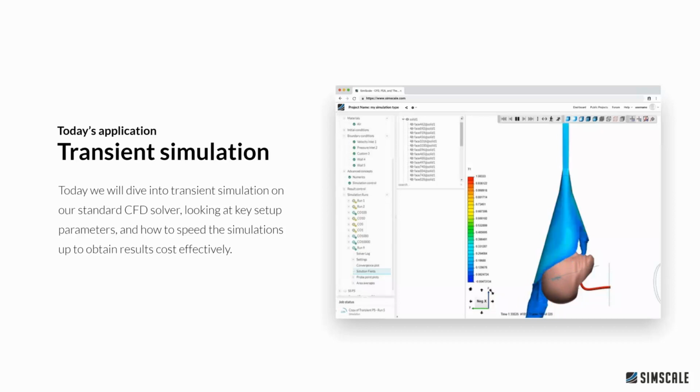So that might include, so this image is showing a man coughing into a tube, and it's showing the actual cough going out of the outlet, but also its flow in the domain as well. So this kind of simulation application is what I'm going to be showing today, and that might include things like transient thermal buoyancy, which can be very unstable. You can analyze that transiently.